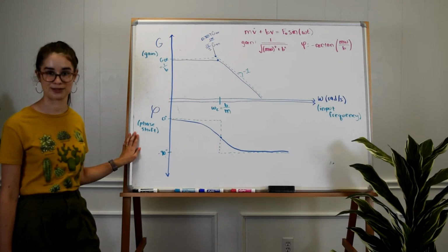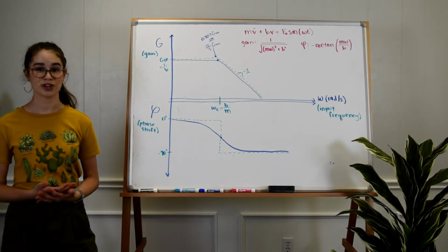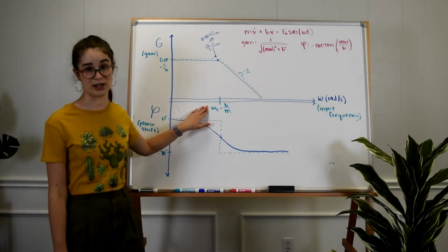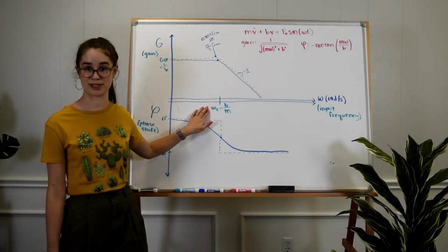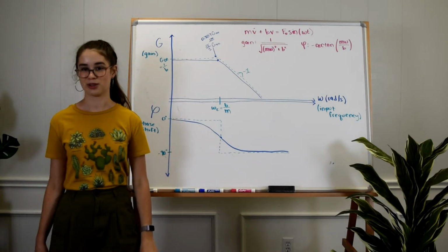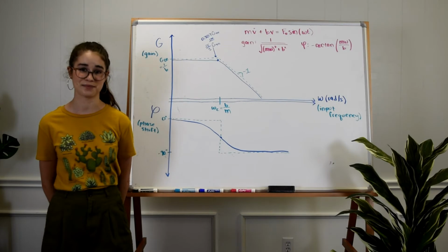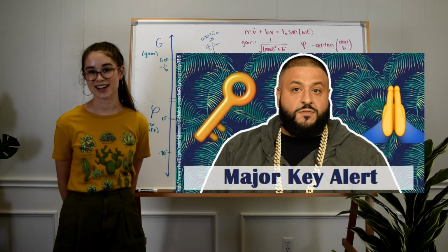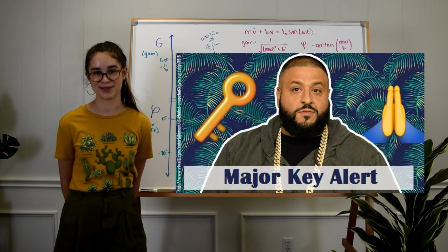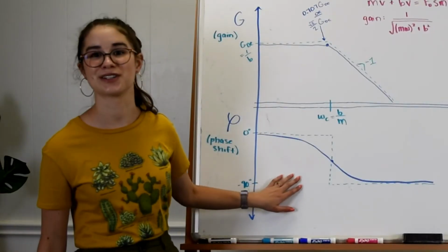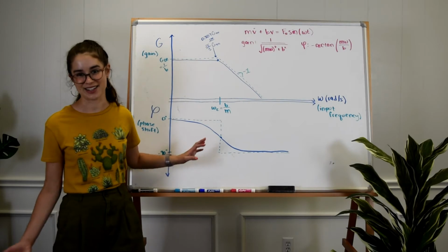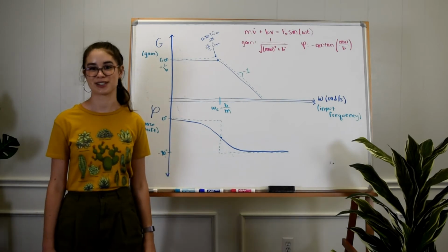Another handy thing is that we can use our Bode plot to find our system eigenvalue, since we know where the corner frequency is. Or we could even use the Bode plot to discuss whether or not two different responses could have come from the same system. Hint here, yes, I had to do all of these things on exams, and they would probably be good things to know. You know, the Bode plot is our friend. But I digress. Let's move on to second order systems.